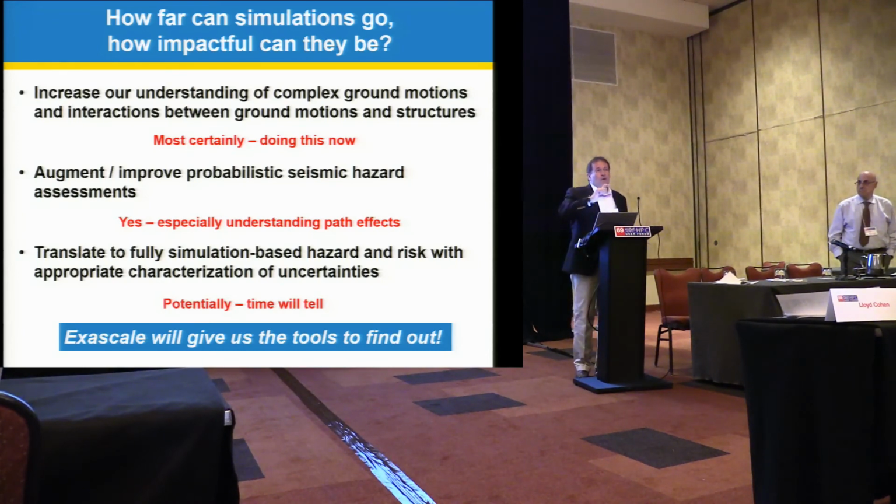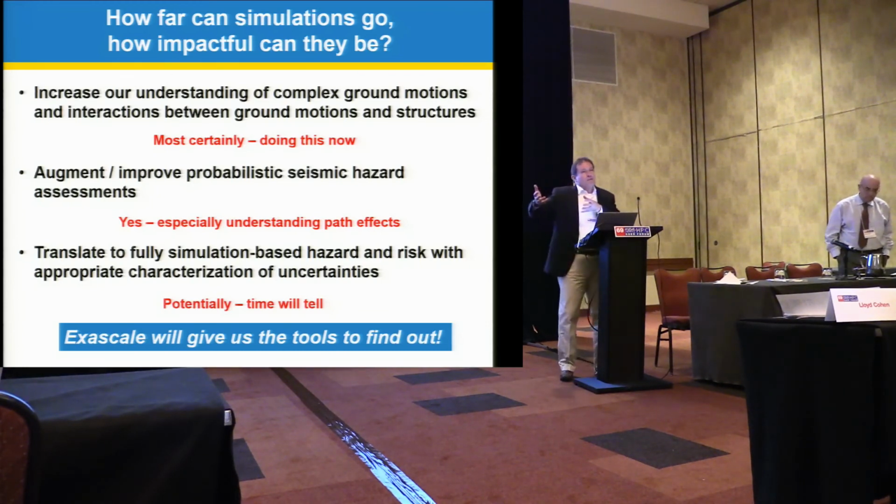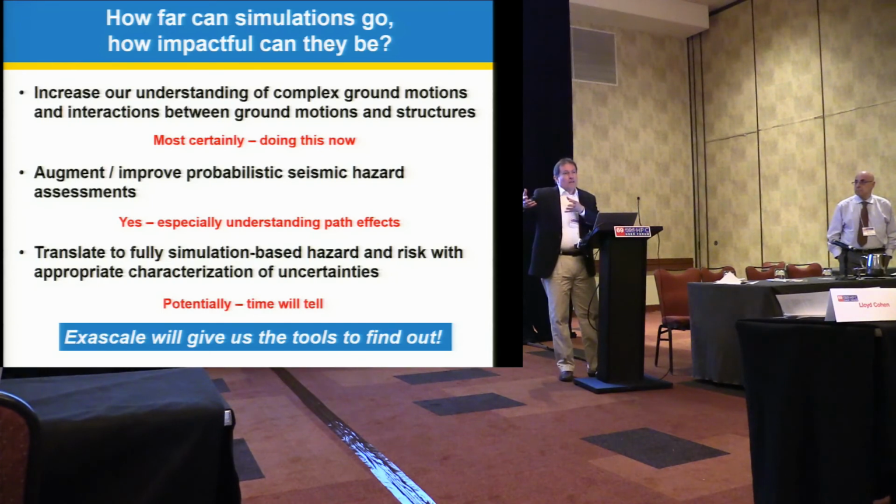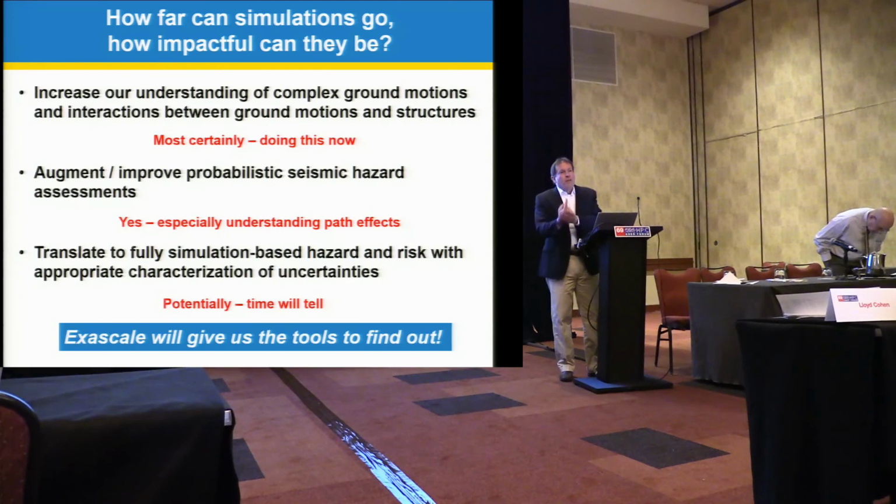Conversely, for a nuclear power plant, and we just had a paper that went out in Earthquake Engineering Structural Dynamics, one of the values of the simulation, as I mentioned, is you would like to understand what the incident seismic waves impinging on that site look like. Traditionally, because we don't understand that, we've just assumed that all the seismic energy is essentially arriving as vertically propagating shear waves. And we know that's not true, and people have done approximations.